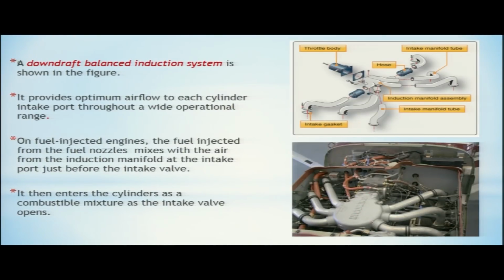From the induction manifold it goes through these induction tubes to the inlet port of the cylinders. This air is provided through these induction pipes, and the fuel is provided through a separate stainless steel line to the intake port. It then enters the cylinder as a combustible mixture as the intake valve opens.